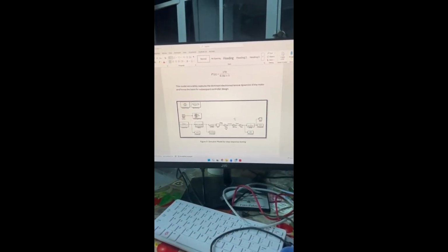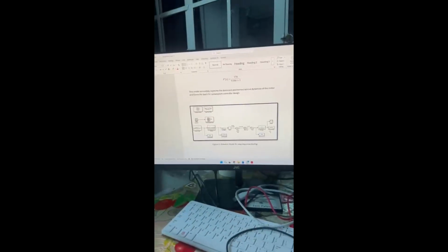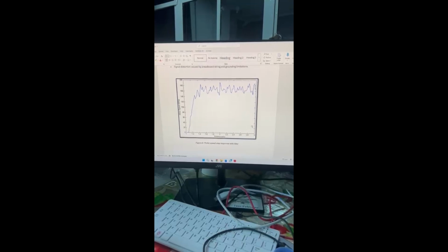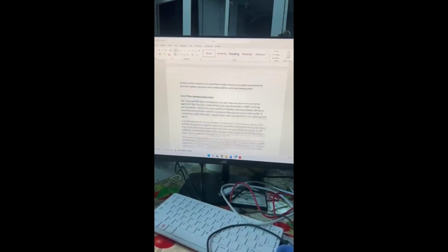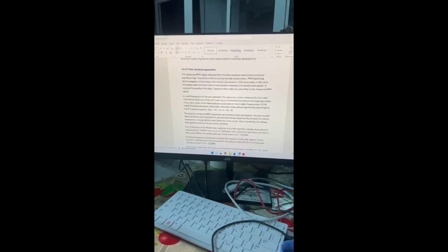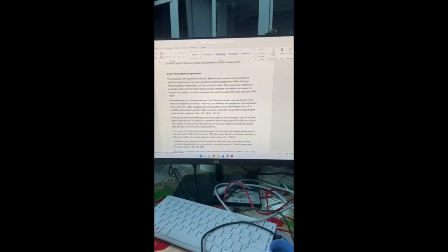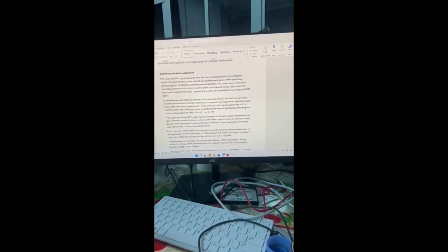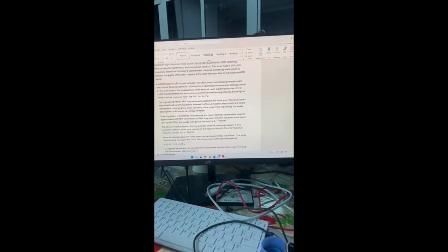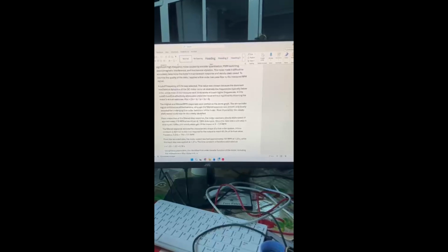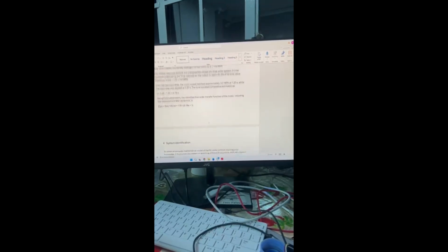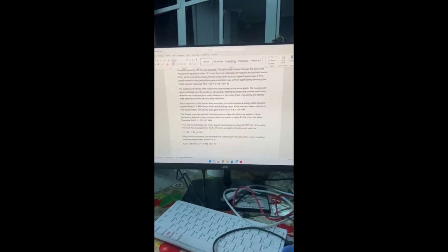Here is my Simulink model with filtering. As you can see, I created some filtering blocks to quote unquote clean the data, and here is the graph with filtering. And for a little bit of an explanation, I just measured the signal obtained from the step response, and I included PWM switching, electromagnetic interference, and mechanical vibration. And I chose a cutoff frequency to help improve the readings, and I did some calculations and it helped me to smoothen out the graph.